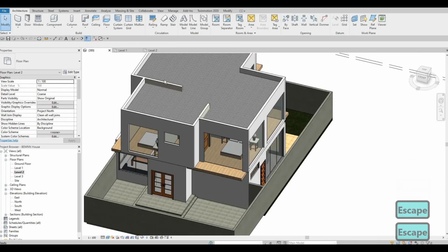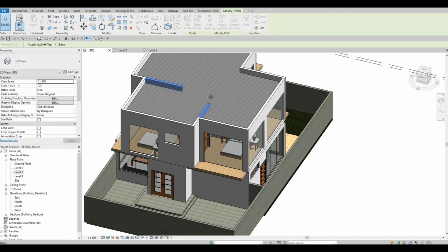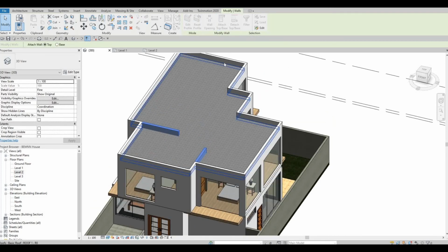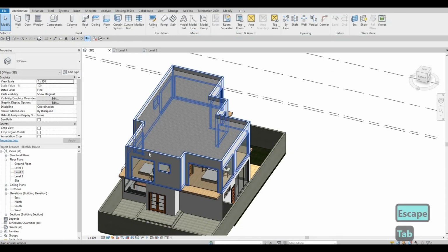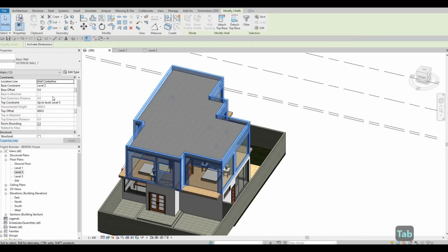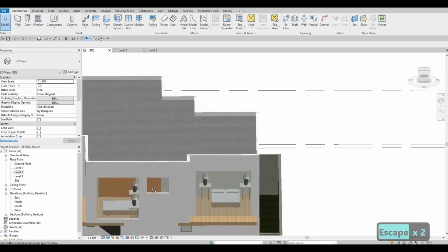Now when we go to here, we could basically pull this down. So select here and select there, click attach top base, and then select the roof. It will disappear. And then now you can select all the exterior wall again, and you can manipulate from 400 if it's too high, to your liking. So it will look like that.